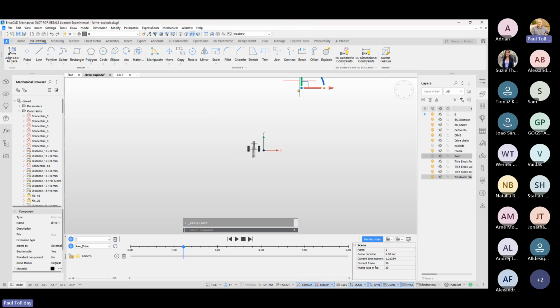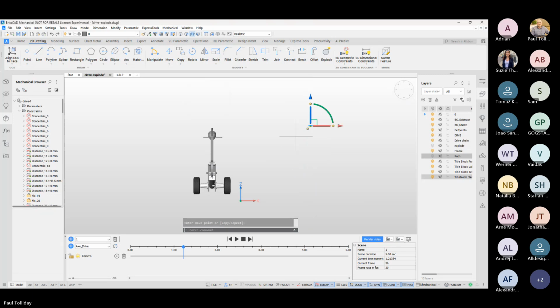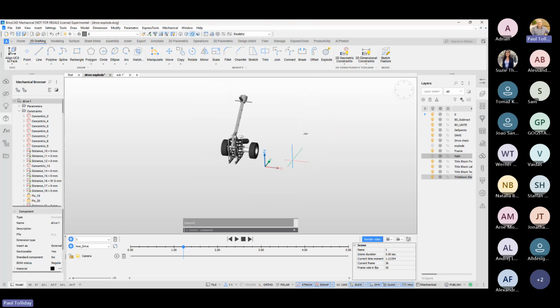Go to our quad. And then we're just going to drag that work point to the position that we want that to be. A bit better. We want to be looking down on the view, so we're just going to move our work point up. Like so. Once we've done that, we can now place our camera or camera effect in here.